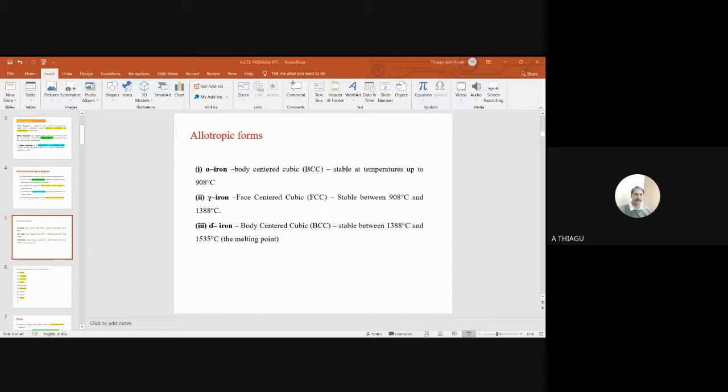The third category is ductile cast iron. Sometimes it is called nodular because the carbon is in the form of nodule-like structures. Can you see that? The remaining part is the matrix, in the sense of alpha ferrite. So what is the uniqueness?